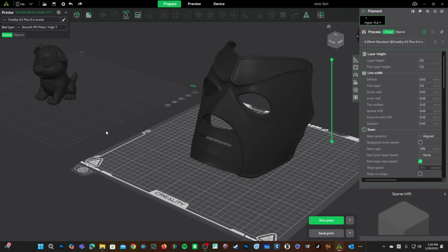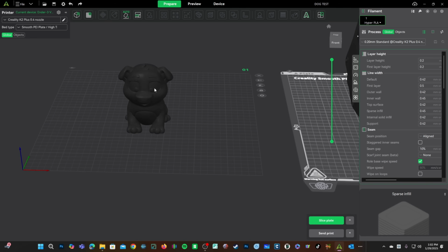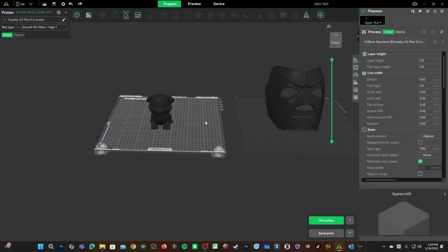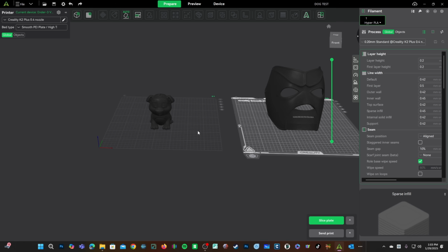This is a useful tool, not only for getting the proper angle for printing, but also for controlling the position of the model in the event you don't like where your Z-seam is placing. Rotating the model can give you additional options in an effort to relocate and hide that Z-seam. But Mr. Rundown, what is this sorcery?